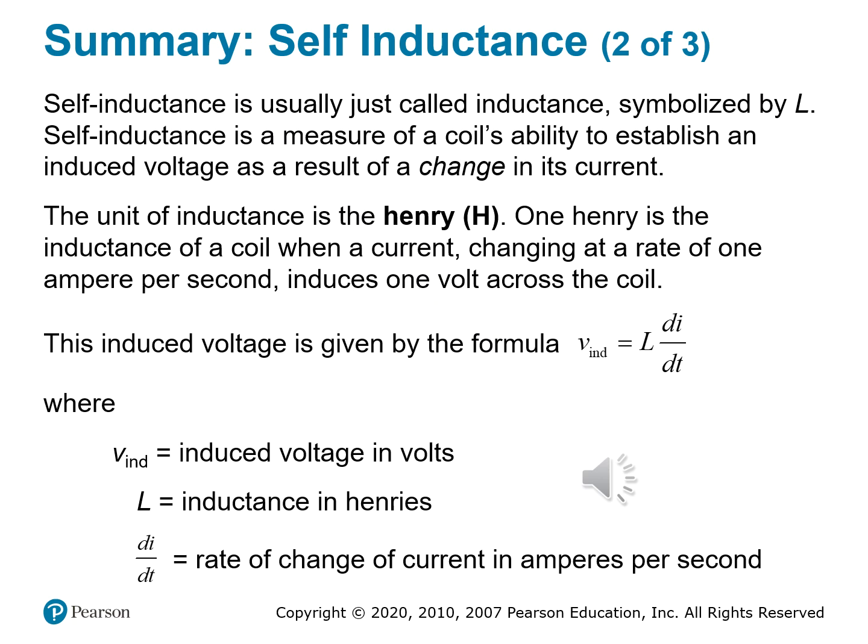The simple idea, or the deep consequence, the key to the equation for induced voltage is that you have an induced voltage equal to the inductance, designated by L, times the change in current over time, or dI/dt, for those of you who enjoy calculus like I do. So induced voltage, V sub L, is the induced voltage in volts, L is the inductance in Henrys, and dI/dt is the rate of change of current in amps per second. This equation is central to understanding how inductors behave in time-varying circuits.